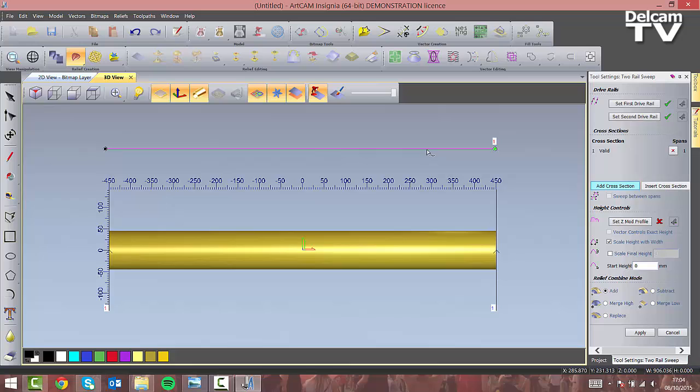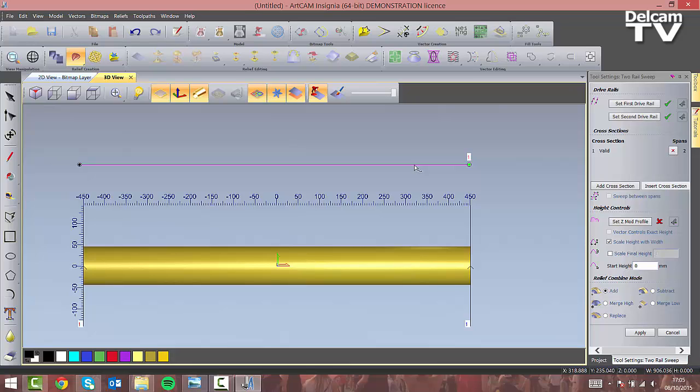Now nothing will change in the model because this is just a horizontal line. To modify it, we can start to insert some nodes and play with them. Let's insert some nodes by pressing I on the keyboard. We can insert as many as we want, so let's insert a couple more. As you can see, there are black dots. This indicates that these are not smooth nodes. We want them to be smooth, for this part at least. So let's hover with the mouse and press S on the keyboard.